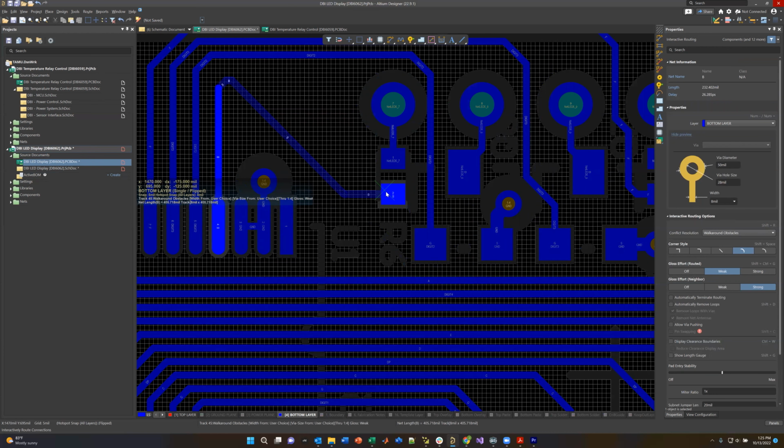Again, also used power and ground layers for everything. So anything that was pulled up from the power plane was direct connections for 5 volts, and anything that was ground was directly connected. Notice though, for this big AC area, I've basically created an island where over here in this corner of the board, there is no copper except for the connections themselves to the terminal block.